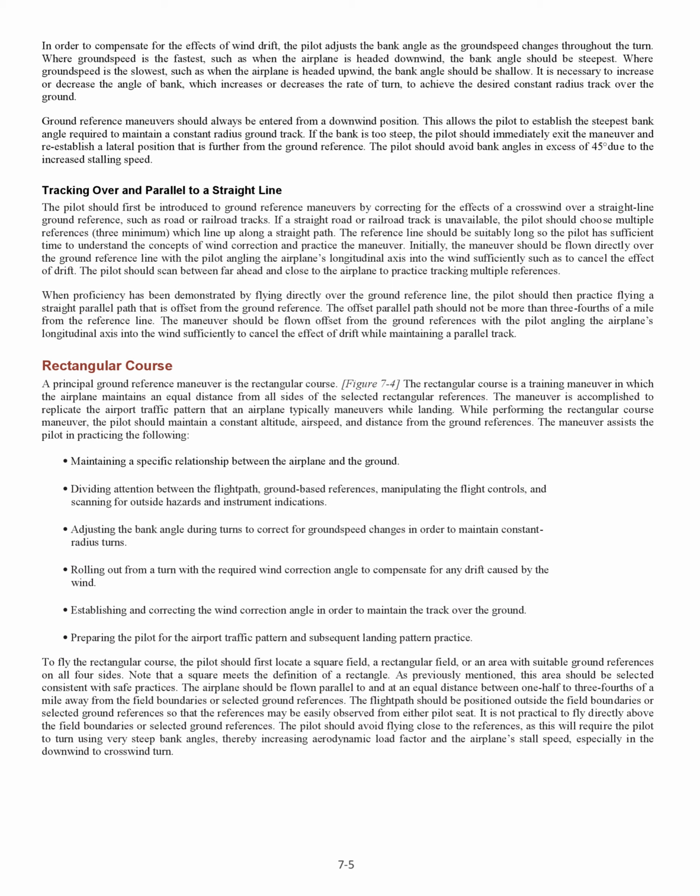Initially, the maneuver should be flown directly over the ground reference line with the pilot angling the airplane's longitudinal axis into the wind sufficiently such as to cancel the effect of drift. The pilot should scan between far ahead and close to the airplane to practice tracking multiple references.